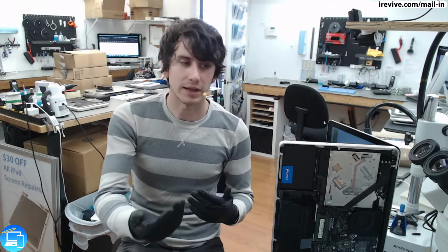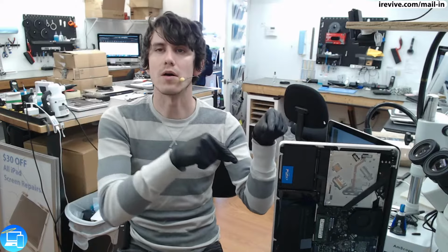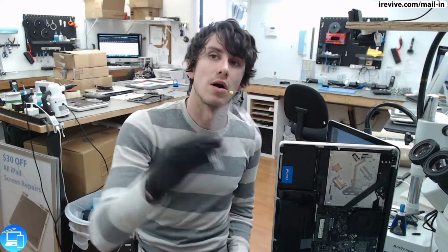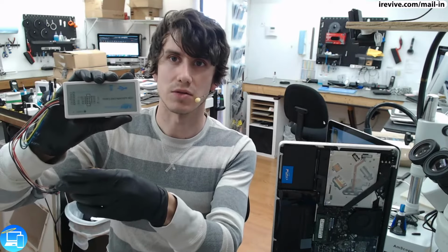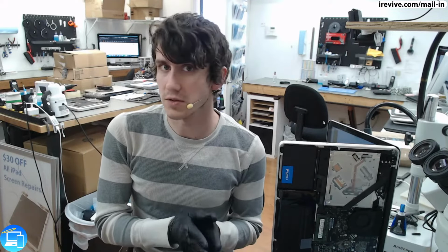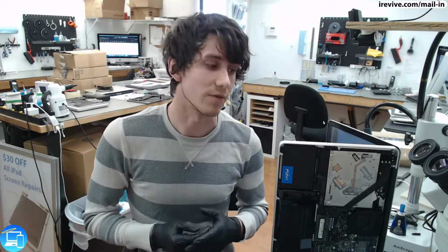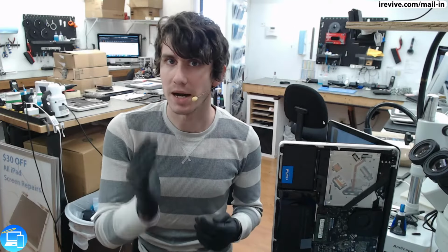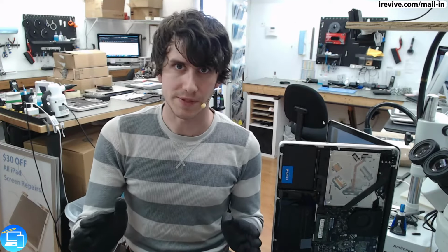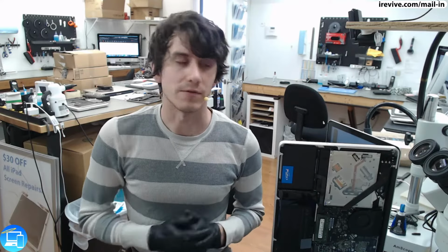Just a quick little rundown again. Basically what we did is we soldered on a new Molex terminal on our logic board. We then used our Lattice programmer, connected this to our terminal next to the Gmux, and then we downloaded the software from DOSDude1.com. Under resources, there's a whole section that talks about permanently disabling the 15-inch and 17-inch 2011 MacBook Pro GPU. You buy the license key for $20, download the software, make sure that PLT_RST_L is shorted to ground. All this is on the website, and then run the flash software.